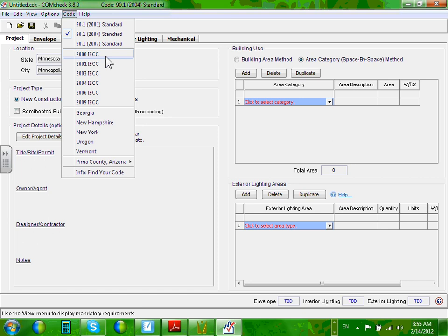That's the default. Now, when you do it in New York, you might have to ask the city of New York, the state of New York Department of Energy, if they have one, or the Department of Labor and Industry, what code they use out of these IECCs or ASHRAE. A lot of people use 90.1. These are all ASHRAE, very, very common. I believe in Minnesota we're using ASHRAE right now, 2004, and 2007 is coming.